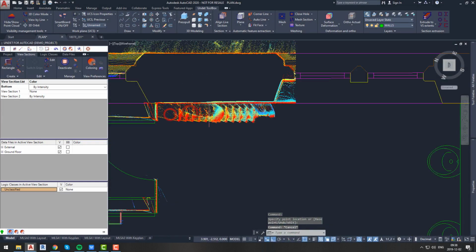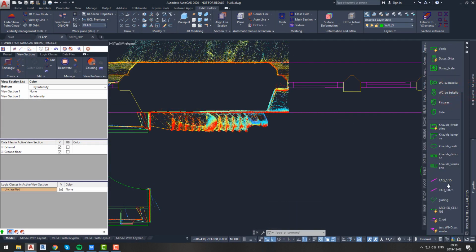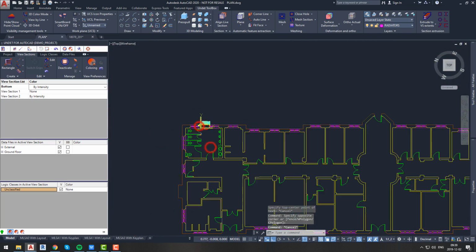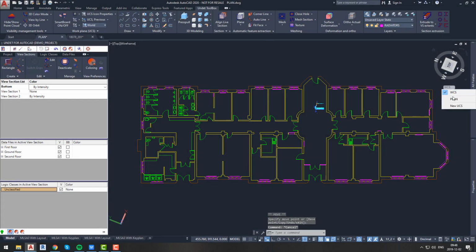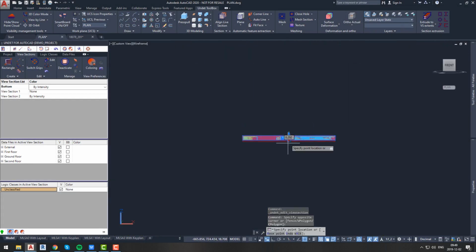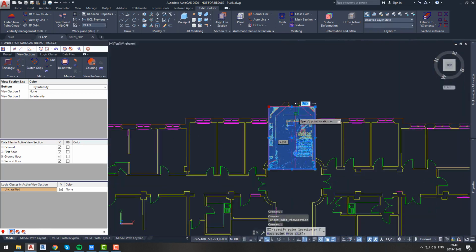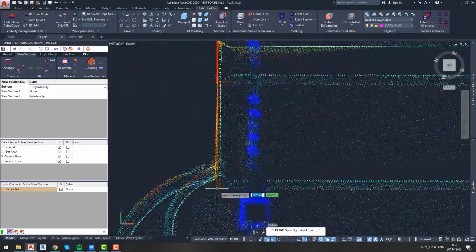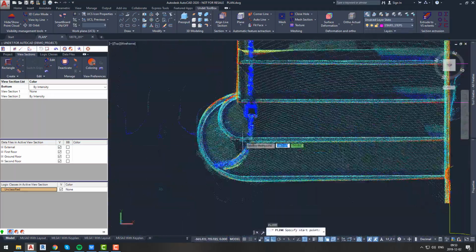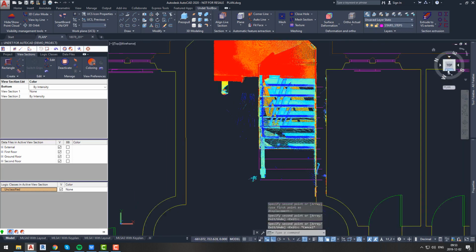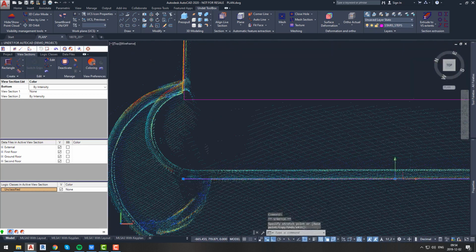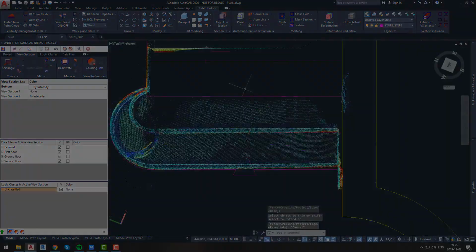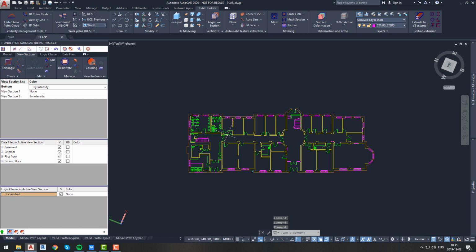Let's add radiators and locate them in our plan as well. Now we should add stairs to our plan. Since this building has 3 stories, there will be a main staircase, but do not forget to look for any other stairs and draw them as well. We should always specify the direction in which our stairs are going up or down. To do it, we use a triangle and annotate the stairs direction. Let's take a look at our plan with all floor objects added.